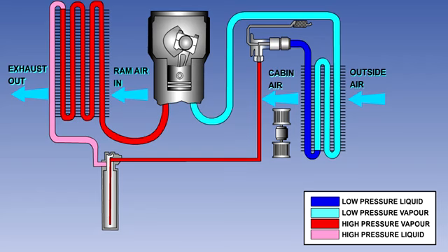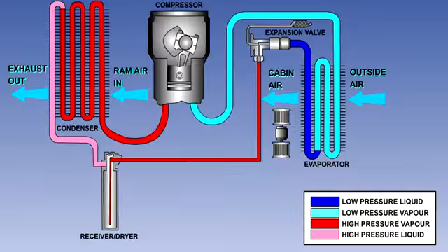The refrigerant is a liquid which boils at approximately 3.5 degrees Celsius at sea level atmospheric pressure. At higher pressures, the boiling point is increased, and vice versa. The major components of the system are the evaporator, the compressor, the condenser, the expansion valve, the receiver, and the electrically driven blowers which pull outside air into the aircraft across the evaporator.